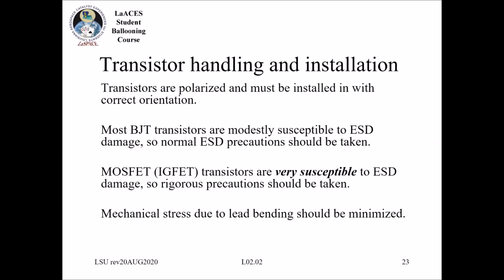The transistors are polarized and must be installed in the correct orientation, and they're modestly susceptible to ESD, so definitely take ESD precautions here. And then apparently the MOSFETs are very susceptible to ESD. And again, with all of these IC components, there's mechanical stress as well, so swap them out if they look badly bent and you want to use them for a final configuration.